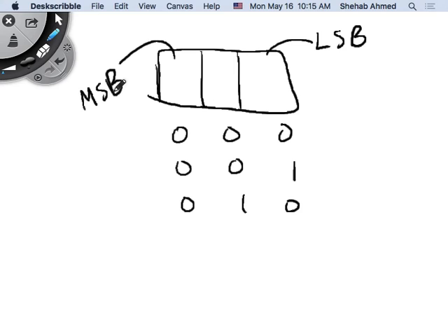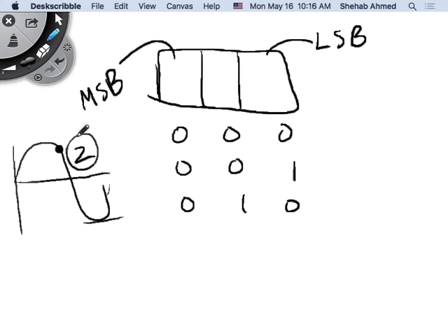And the way we go from the sine wave to the value that we measured here. Let's say I measured something that's equal to, remember we said we're only limited to 0, 1, 2, 3, 4, 5, 6, 7. So let's say I measured 2, right? What will this 2 correspond to in this digital storage bin that I have? I measured 2. Yes, it will correspond to 0, 1, 0. So this is 0, this is 1, and this is 2. So how did we come up with that?